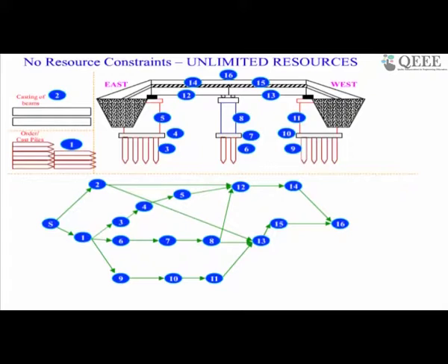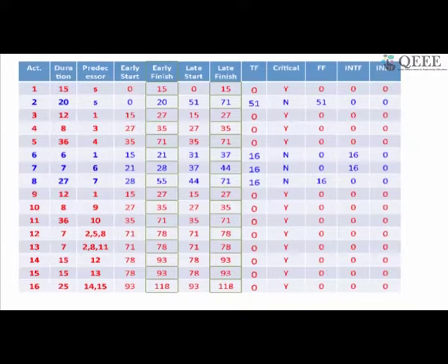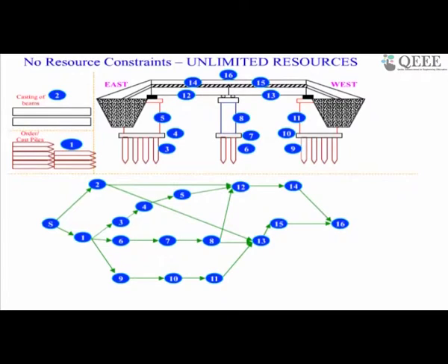So the relationship I have shown here, while it's physically acceptable because I have said unlimited resources, might not be practically doable, because the contractor would say I want to first do 3, then do 6, then do 9, which means my resource relationships between these have not been captured. Unless I load resources to this plan, I will not really be able to get a proper duration. Here I have shown you the duration calculations. I get some duration, but it is based on unlimited resources, which is not realistic. So really we need to start understanding how to load resources and how to bring resource requirements in.